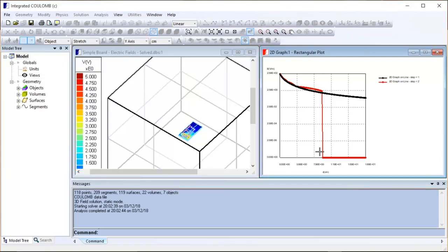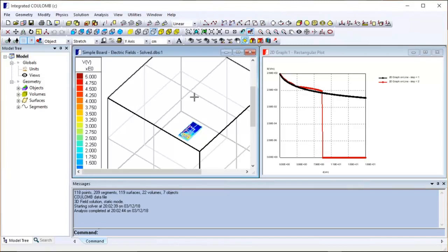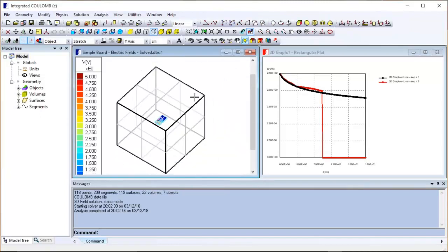So finite elements works on some artificially bounded space where boundary elements only needs to mesh the actual geometry and can therefore predict the fields anywhere automatically. One doesn't have to mess around with boundaries and mesh gradients in order to get good results far away.